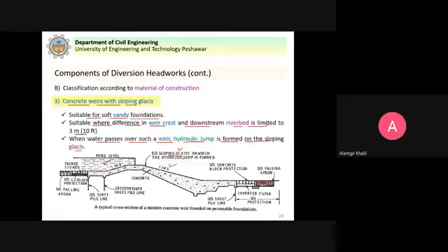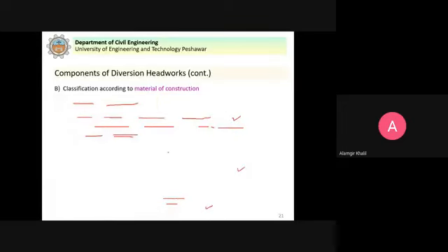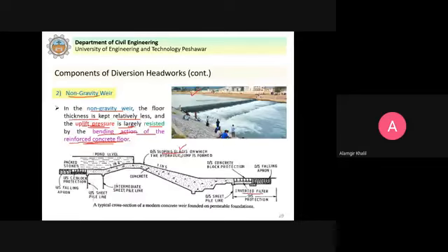Just like you see here, I show you in this practical picture, actual. You can see the hydraulic jumps that occur here and dissipate the energy. Otherwise, if we do not have protection here, and this is also called the stilling basin.